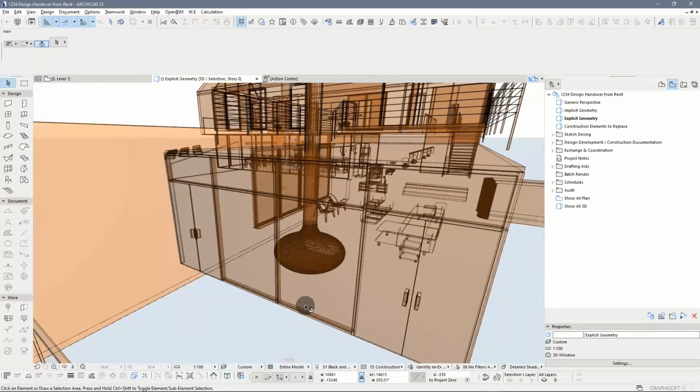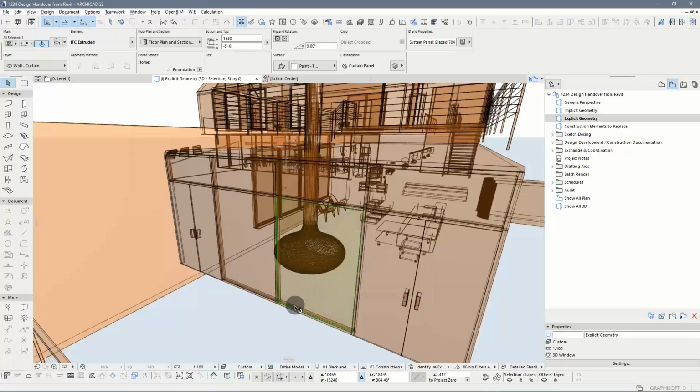could be done better if computer power allows in the future, the curtain walls typically do not come through as explicit geometry. So rather, you'll see that here, every panel and frame tends to be built with either morphs or objects, even though the IFC recognizes those things as extrusions. And again, that's usually due to the nature of the two different tools, both in Revit and the way Revit builds a curtain wall and the way Archicad will recognize that and build its own curtain wall.